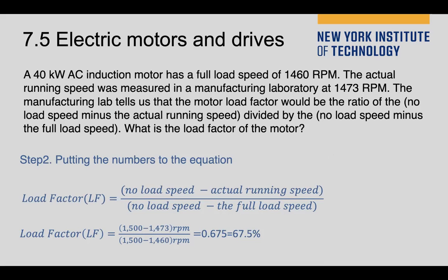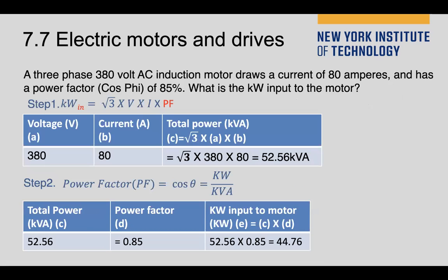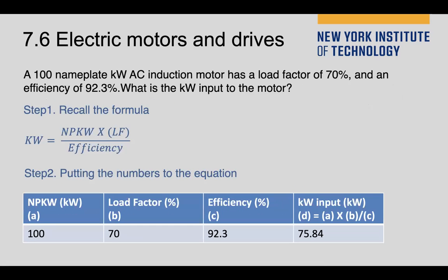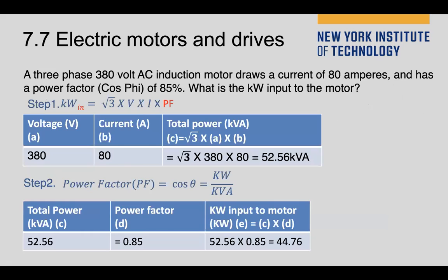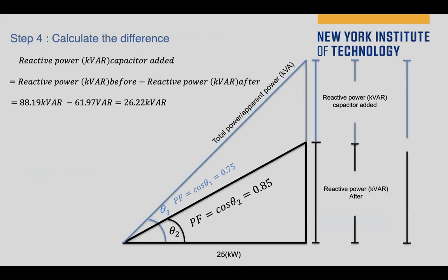I remember even in your notes or in the books it has this equation, but try to remember this and know how to use it, because sometimes it just gives you the speed, then you need to calculate the load factor. If you can handle those relationships, load factor, efficiency, and power factor, then almost all the questions here you can settle.